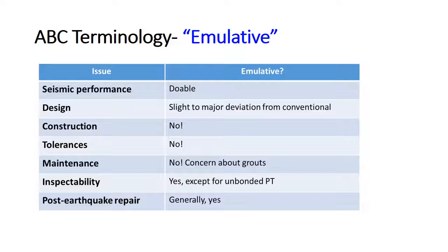The construction is definitely non-emulative because it's very different than what we use in cast-in-place construction. Tolerances are also very different. In having precast segments, we have to make sure that these precast segments fit and the connections come together in the field. That requires relatively tight tolerances.